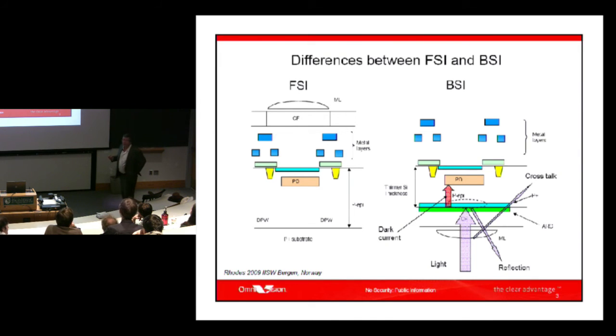Another trick that we developed is what's called backside illumination. My kids really giggle a lot when they hear about backside illumination, but for some reason that's a historical term. So here's the cross section we just looked at with the color filter array, a microlens, and a cross section of some wiring. We're trying to get the light down to this photodiode, so it's got to go down a long way. But it also has implications for the optics, the main lens: the angle the light comes in can't be too steep or too oblique and still manage to get down here.